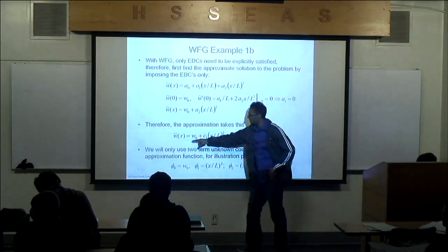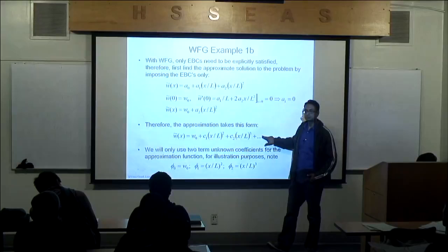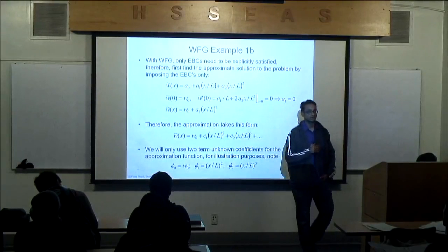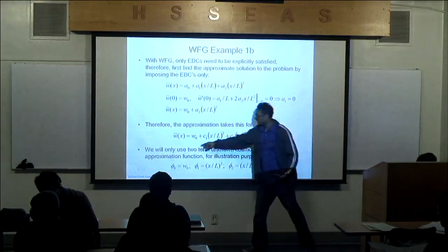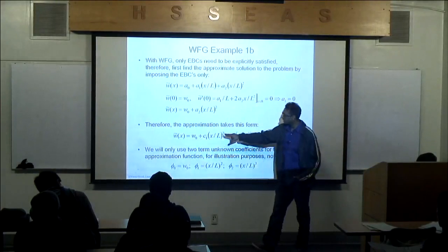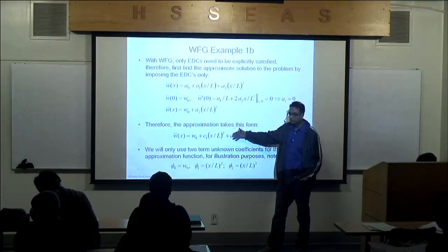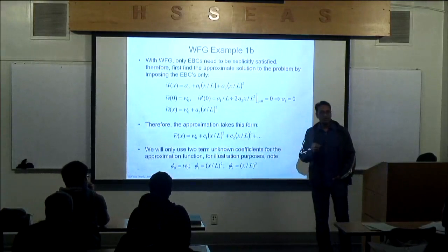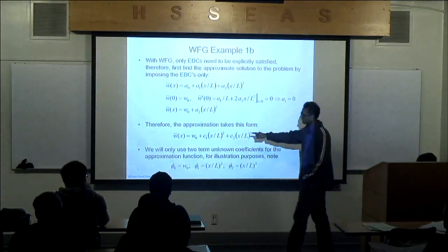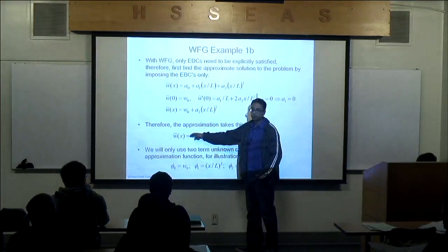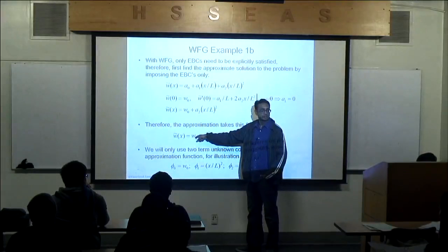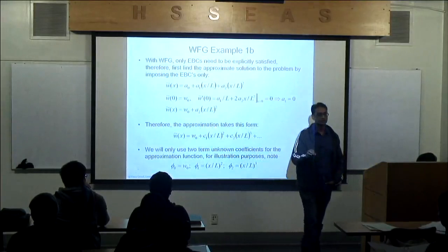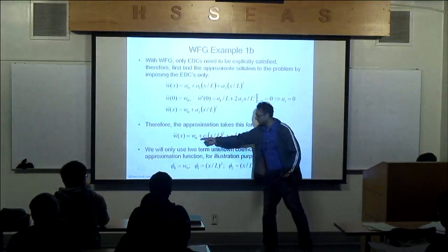And so now let's check it. At x equals 0, what happens? I get the boundary condition that we talked about, W naught. For W prime, if I evaluate it at x equals 0, this is going to work out, trust me. It's going to give you 0 also. So that's great. And notice how I have this extra term here. This is your phi 0. Remember I told you that if I specify a non-zero value on an essential boundary condition, this phi 0 is going to show up.